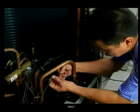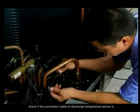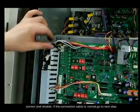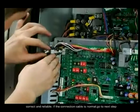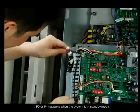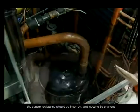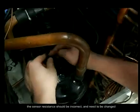Step 1. Check if the connection cable of discharge temperature sensor is correct and reliable. If the connection cable is normal, go to the next step. If P0 or P4 happens when the system is in standby mode, the sensor resistance should be incorrect and needs to be changed.